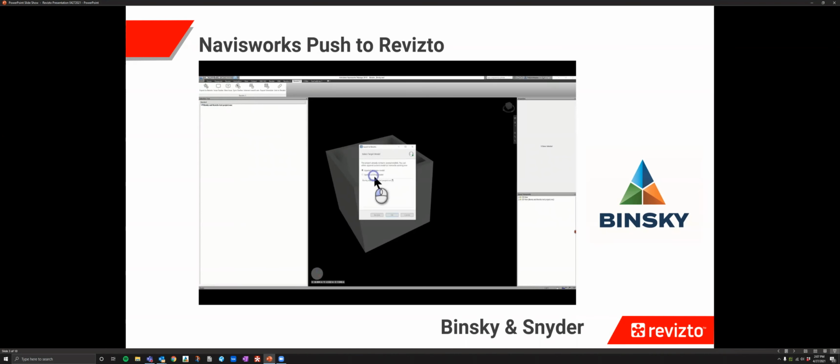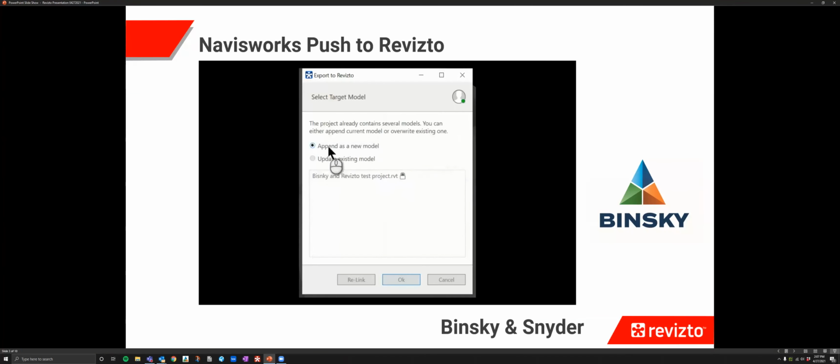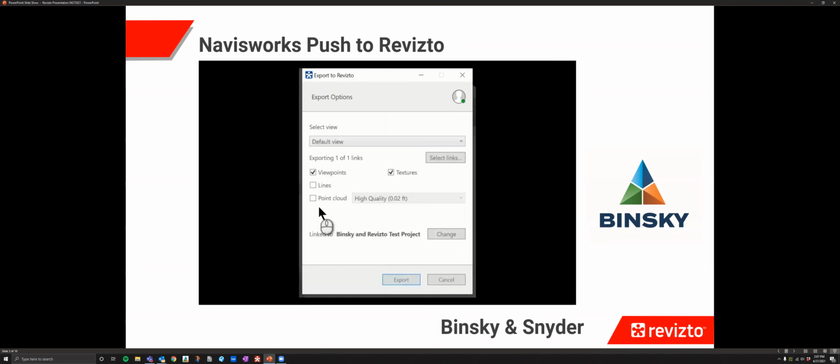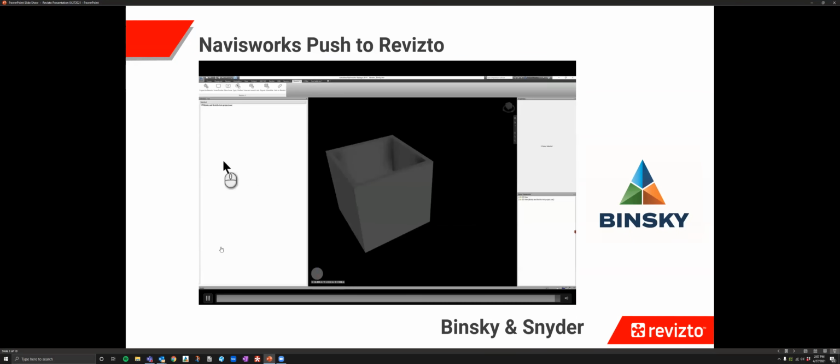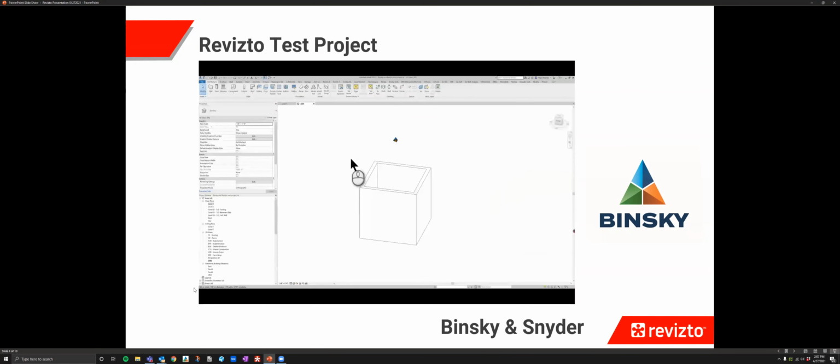And whenever you're doing this, you always want to append as a new model. So you're pushing something new. I had done the Revit one before, kind of did little videos backwards, but you're going to push the NWC. It's going to show in the project. And then after this video, Dan's going to open the Revit one. Okay. And then you can do the Revit one. And there you go. Those are the 4 boxes.